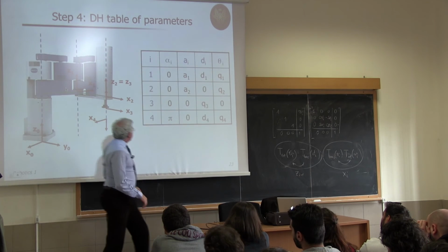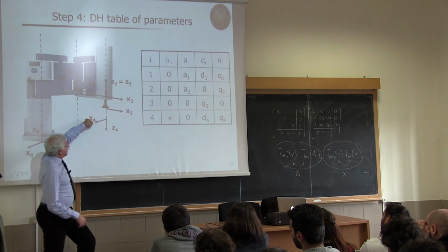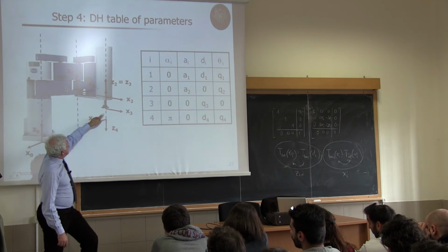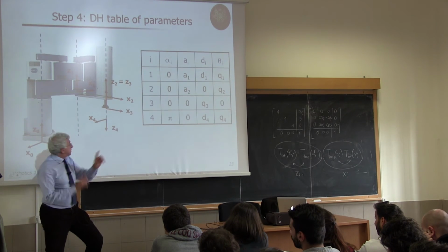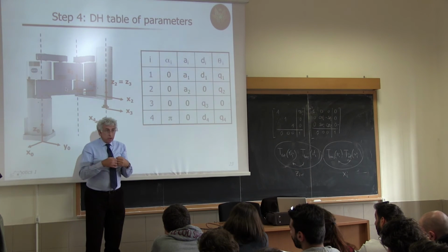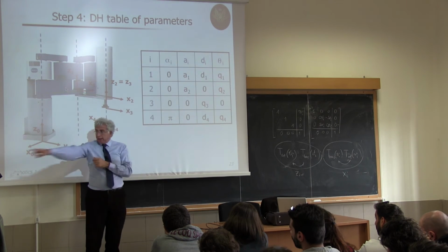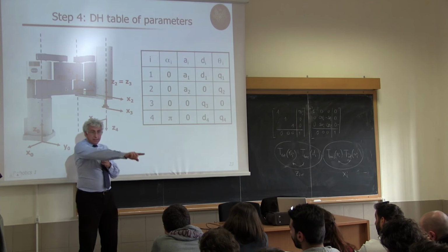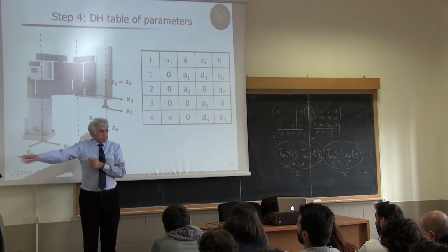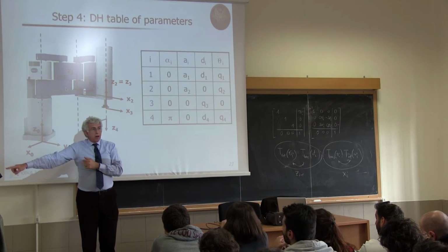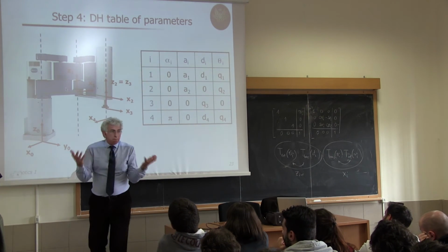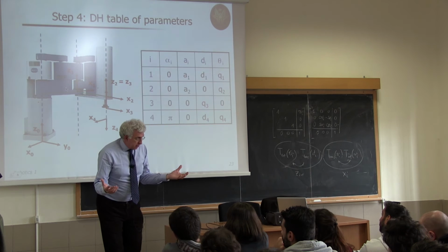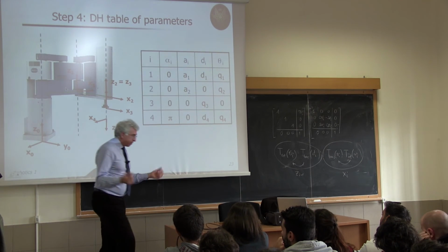This is theta 4, it's a variable, so it's the angle between x3 and x4, as seen from the joint axis. The joint axis is the fourth joint axis, so it's Z3. So I'm standing on top. I see x3 going almost 90 degrees over x4, but rotating clockwise. So this value in this configuration will be minus 90. Okay?